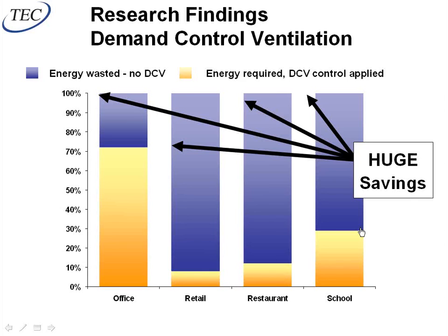Then they come back. So throughout the day, on, say, an 8-period day, they may only be in their classroom for 5 or 6 periods. And every room in the school is like that, where people are moving in and out. Normally, you have to design every single room as if every student was in every room. But everybody can't be everywhere at every time. Everybody has to be somewhere, and only one somewhere. So you can pretty much modulate all the rooms back when the students aren't in there, and there's a huge potential savings.